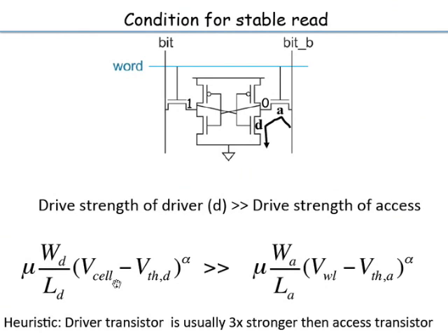So this current drive should be much bigger than the current for this transistor, right, at the same voltages. So then you know that what that means is that the VDS required to support a particular current is not much. Okay, here actually I should have put VDS also, then it would have been clearer.